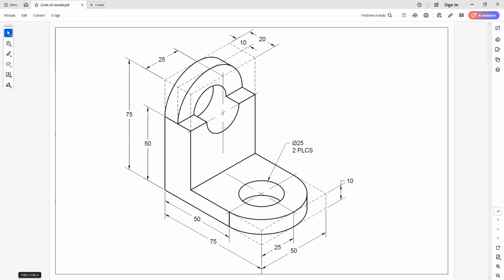As far as this drawing goes, if you take a look at the drawing that we did using AutoCAD 2D, we drew it using the standard method of putting a title block on. Now, by default, when we use the 3D method, we're going to be forced to use paper space, mainly because we have to select on the base icon. So anytime you're using AutoCAD 3D, you're kind of forced to go that direction, right?